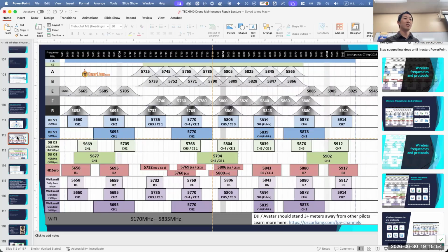And I'm not even talking about designing from the ground up. I'm just saying you want to build something with existing components. Which filter or drop-down do you need to choose to get the right thing? There's the physical size, and then there's frequency. So far we only showed the VTX, but it's the same thing for the receiver. You can buy a 2.4 gigahertz receiver, or you can buy a 915 megahertz receiver. If your other controller is not the same, it's not going to talk. It's got to match frequency, and it's got to match protocol too.